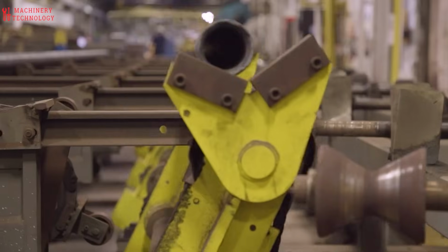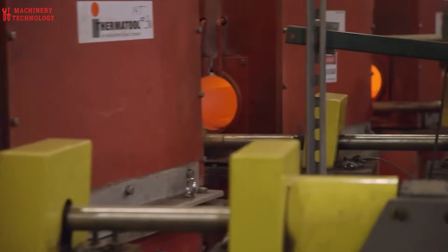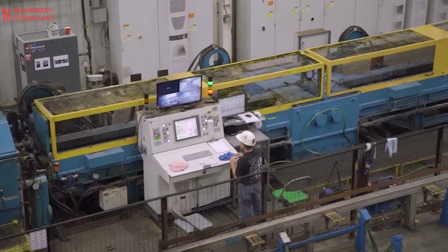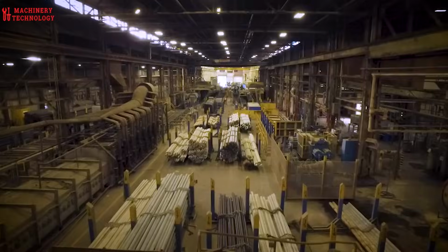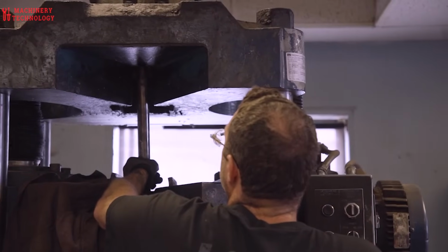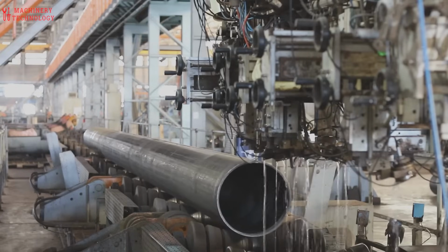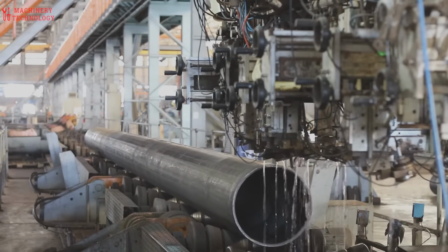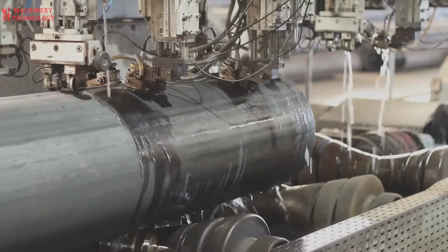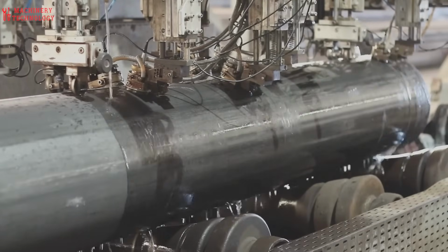The cold drawing process creates a uniform, precision product with substantially improved tolerances, surface finish and tensile strength, increased hardness, and good machinability. In this process, the tube is cleaned and annealed, and one end of each length is squeezed to a point so it can be gripped by the drawing mechanism. The tube is then drawn through one or more dies and over mandrels. This reduces the diameter of the tube and thins its walls to the required dimensions in a controlled fashion to provide the qualities desired in the finished product.